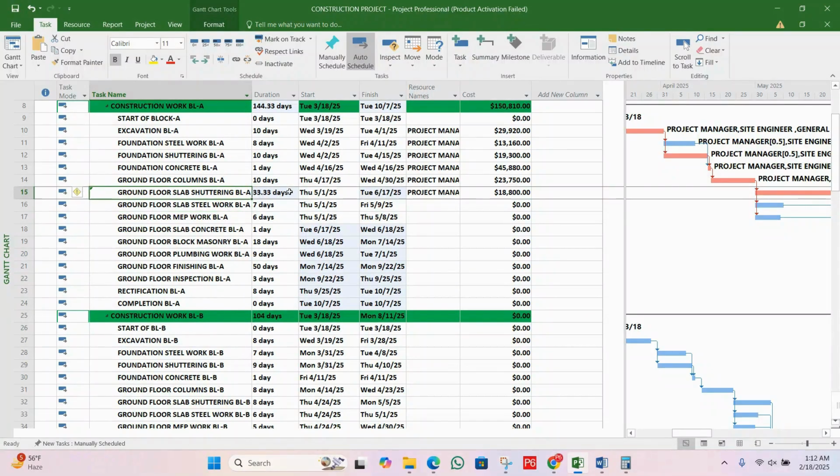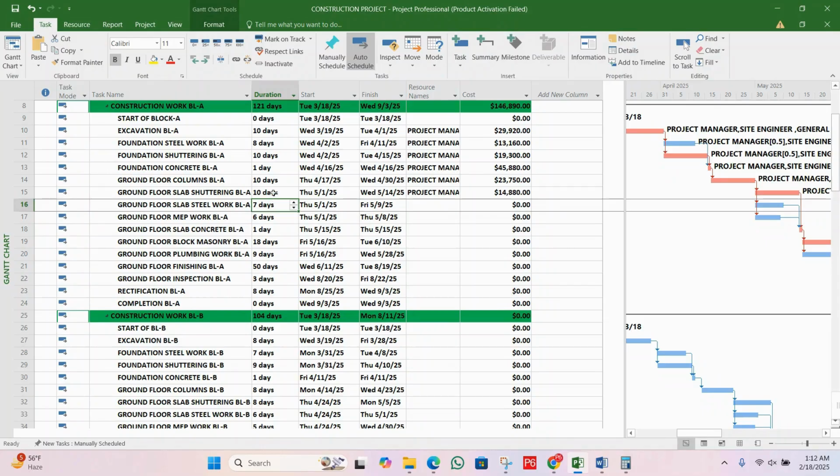You can see, whenever we have just a reduce here, it's going to take more duration. You simply click here and you can click on this option: change the amount of work but keep the duration same. You can see again we will have 10 days. After modification you have to make sure you choose the right option because your duration should not increase.